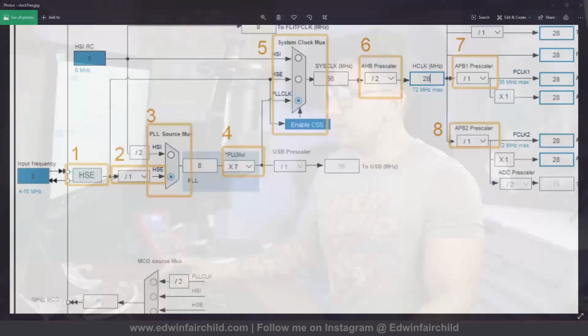So the external oscillator doesn't necessarily have to be a crystal. In fact, that's what these boards do. These boards, well, not all of them, but some of them with the integrated ST-Link, instead of having two crystals, one for the ST-Link, one for the other chip, they just have one crystal and they have the ST-Link output its clock to the target chip. And then sometimes there's a solder bridge in the back or something where you can make that connection, and it'll make the connection from this master output clock into the crystal pins for the target chip. So that's just a little side note.